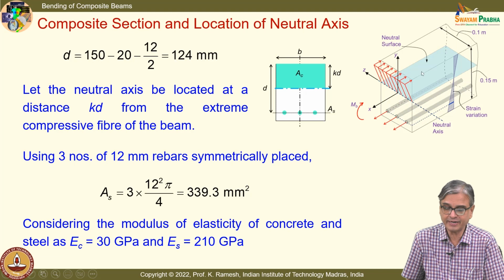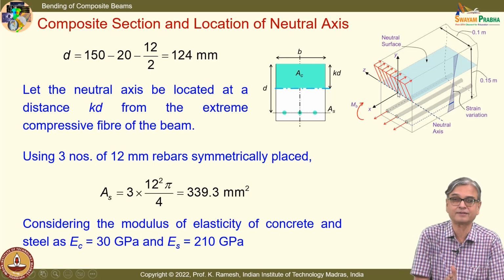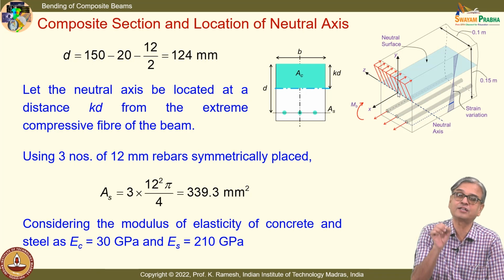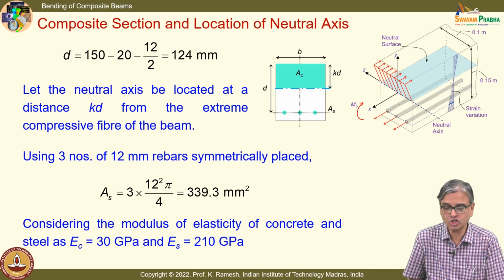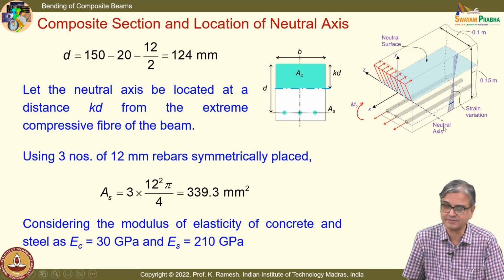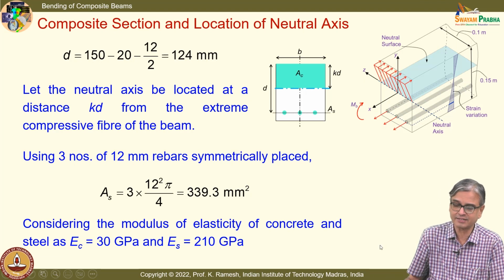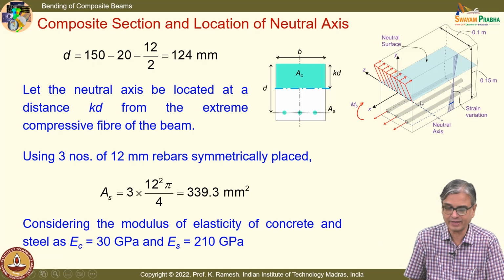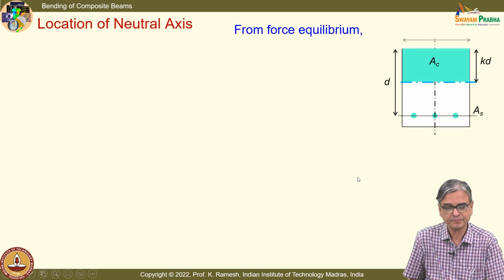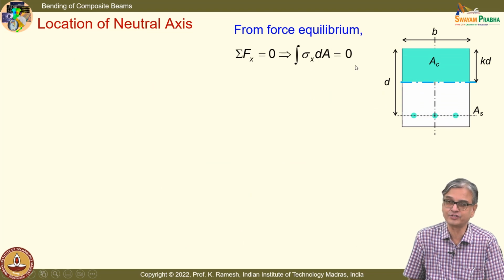See, there are multiple definitions for neutral axis. While developing the strain, we consider this as a neutral axis. You can also consider that when I want to measure from this, we are doing all the calculation only on the symmetry plane. I can also find the neutral point and then go up. Some books also say that you can also call this the neutral axis, whatever line is representing the neutral surface this way. So, it is a very small nomenclature variation. So, from force equilibrium I get the integral of sigma x dA equal to 0.